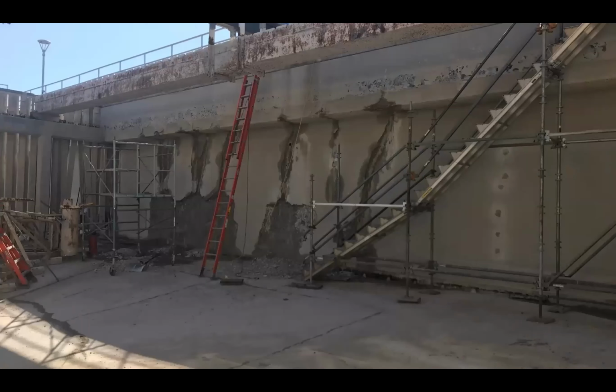So just to give you a sense of this, if you drain the water and you look at this, you can see quite a bit of scaling that's occurring on the walls. You can see cracking in the walls. These happen to be through thickness cracks. You can't tell from here, but we know that by way of investigation. So you've got cracks all the way through the walls, and you have a lot of concrete that is eroding or scaling off of here.